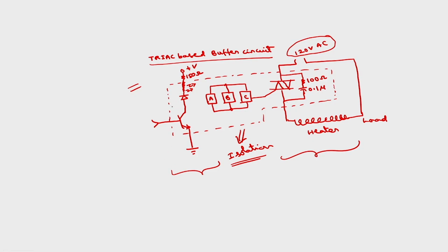So this transistor part from here to here is connected to the microprocessor, and this part is connected to the high power device. There is no connection here at all. Okay. Now how will the coupling take place here? Through this LED. Whenever I apply, this is from the output port of 8255, whenever this LED glows, A will act as a photo transistor.